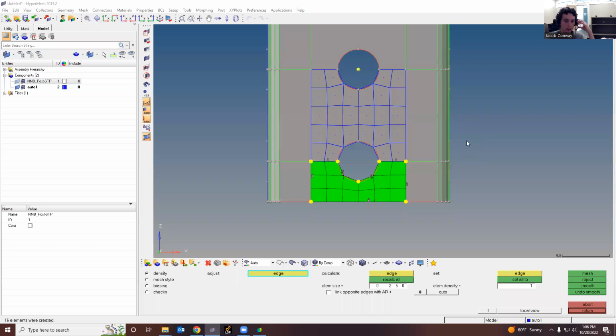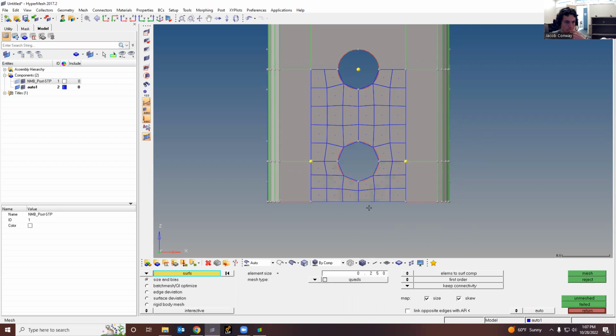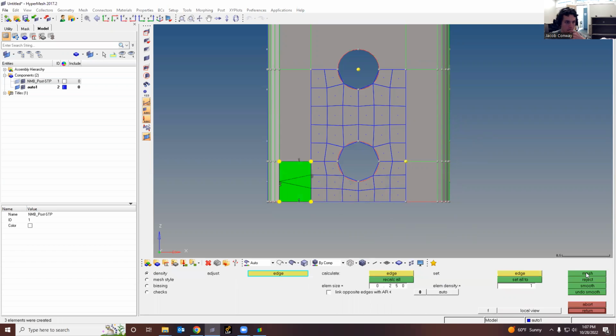All right, y'all. I was playing with that a little bit and figured this out. So with the 1/4-inch mesh size, we can get this pretty good looking right here using 6 on that edge, 3 on that edge, 2, 2, 2, 2. So now you can just accept. Now we can do these edges, see how this works out. We're definitely going to want 2 on each of those. Yeah, there we go.